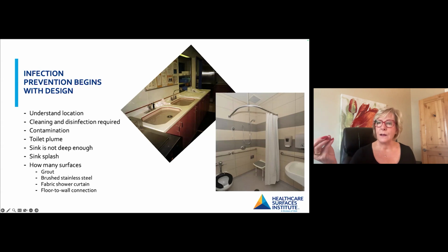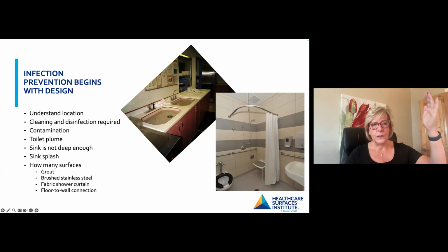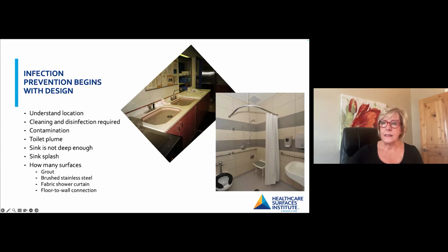So a lot of times when a microbe gets on that, it'll actually attach. And then the same is true with the floor. There are solutions to this. You can actually put, for instance, a solid surface material that can go from the floor to the ceiling and actually cove into the floor. So when it's mopped, the floor is actually getting cleaned and there's not a ridge around the edge that needs to be cleaned and is not done so frequently.